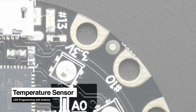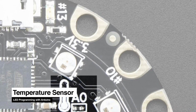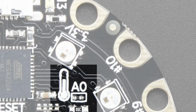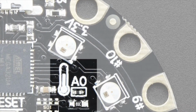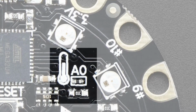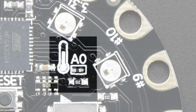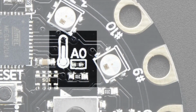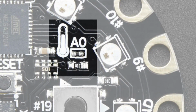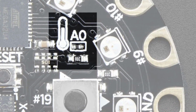It's easy to calculate the temperature based on the analog voltage on analog pin A0. There's a 10K 1% resistor connected to it as a pull-down, and you can read the analog value and calculate the temperature with the beta constant, or just use the Circuit Playground library. The Circuit Playground library has a built-in CircuitPlayground.temperature function, which will give you a floating point number in centigrade. Also, if you need to use Fahrenheit, they have a built-in function for that as well, which is CircuitPlayground.temperatureF. We'll have a look at both of these.